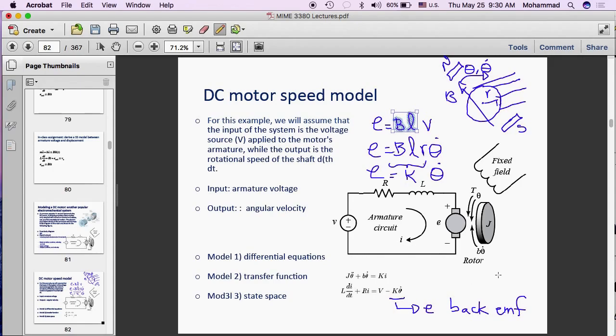Okay, so let's now move to our Newton's second law. What we have here, what says J and B theta dot and theta and T, this is basically the free body diagram. That shows the inertial element that is attached to the shaft of the motor. It's shown as a disc, but it doesn't have to be a disc. Anything that rotates, even the winding assembly itself, has some inertia. So it's everything that has inertia and moves with the motor.